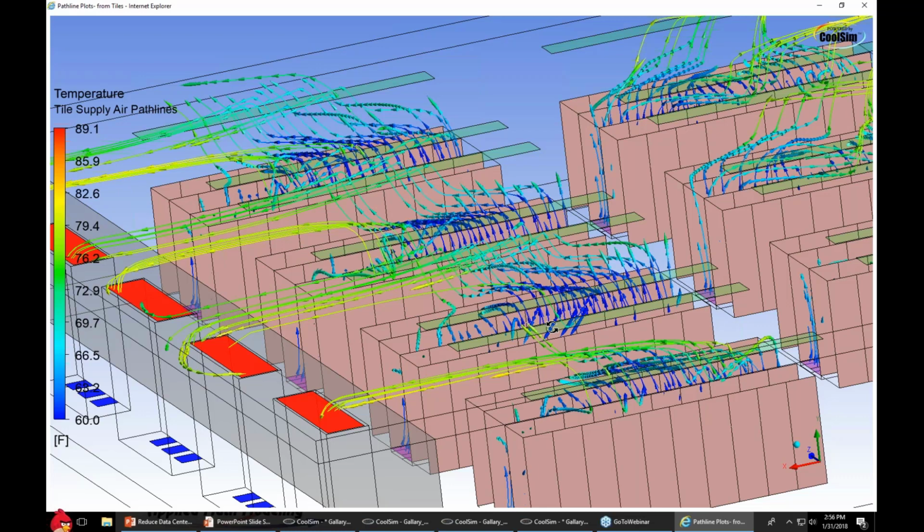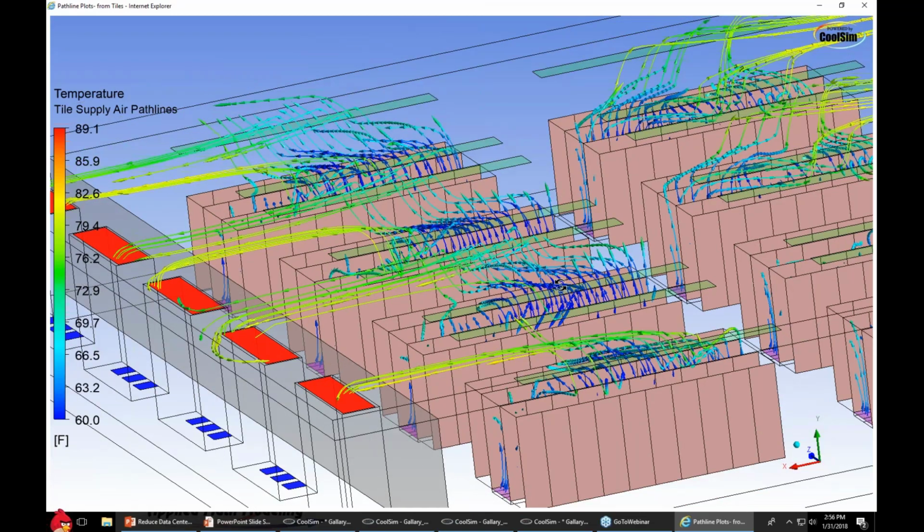What are common thermostat locations seen in the field that are not optimal? I see a lot of junk in the field, a lot of mistakes. It's quite common to see thermostats stuck in the returns of the CRAC units themselves. That's a terrible place for a thermostat. Let me be specific. There are a couple of different thermostats that are typically used to control these things.